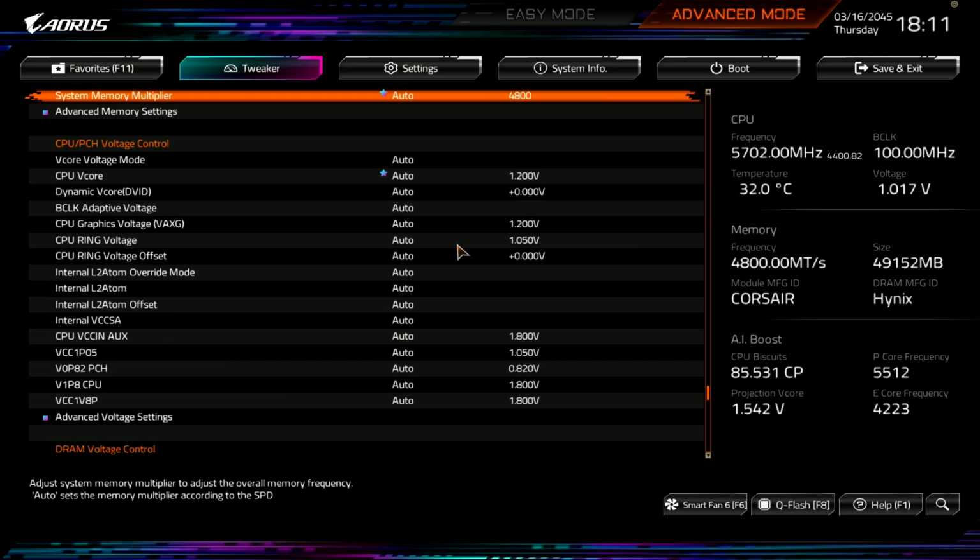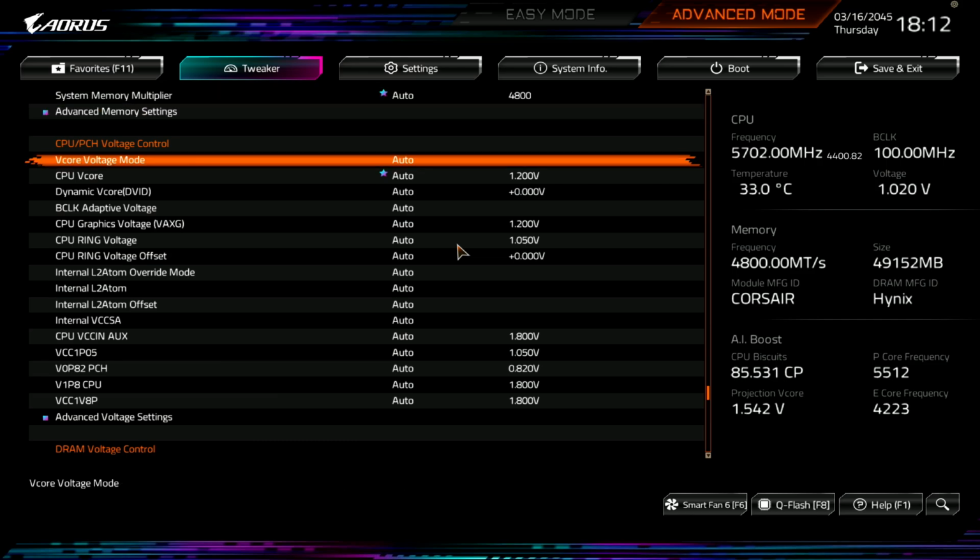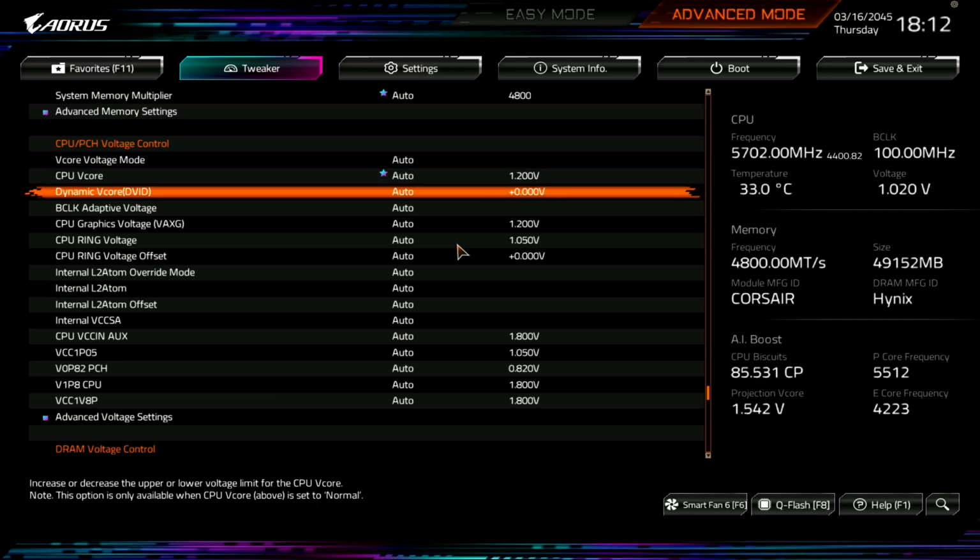And so if you want to be safe, you probably shouldn't be turning off something called current excursion protection, because the Intel documentation doesn't actually explain what CEP is supposed to prevent. It does say something vague about how it's supposed to prevent excessive current, but it doesn't say what the consequences of excessive current are. It's probably degradation, but how much of it? I don't know. It doesn't say. So I wouldn't recommend turning off CEP if you want your CPU to last a long time.